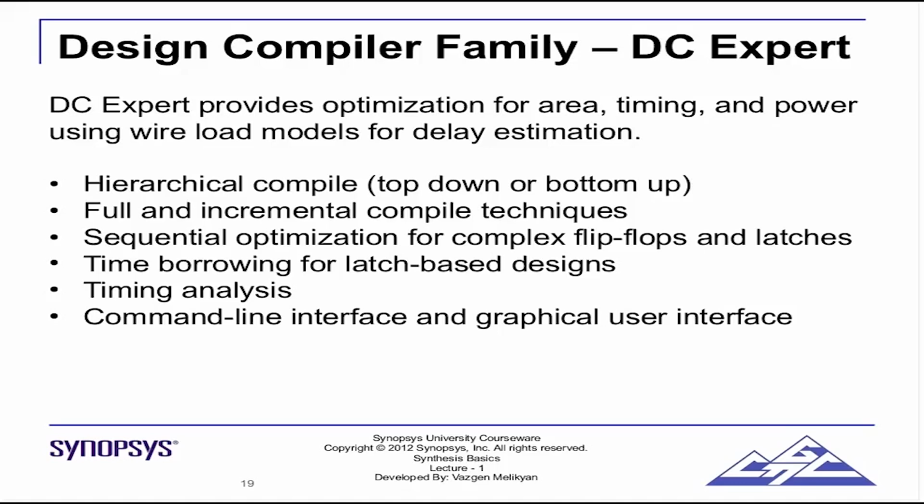So DC Expert is a basic synthesis compiler. It provides optimization for area, timing, and power, using wire load models for delay estimation. Wire load models estimate the interconnect delay. We'll see what they look like. So what capabilities does this tool have? It provides hierarchical compile, that is top down or bottom up. We'll see in detail what that means.